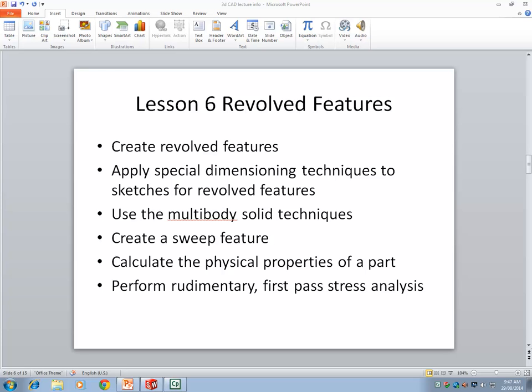For drawing sweeps, in most cases, you'll need a profile and also a path. You move the profile along the path, and your path should not have any self-intersecting sketches. If you have, your profile will not move along the path.